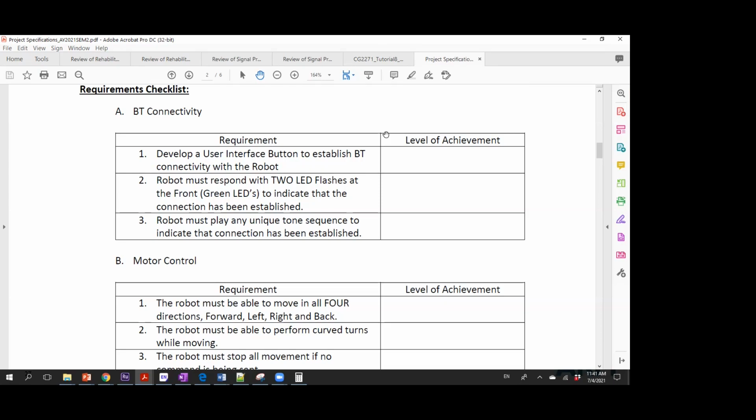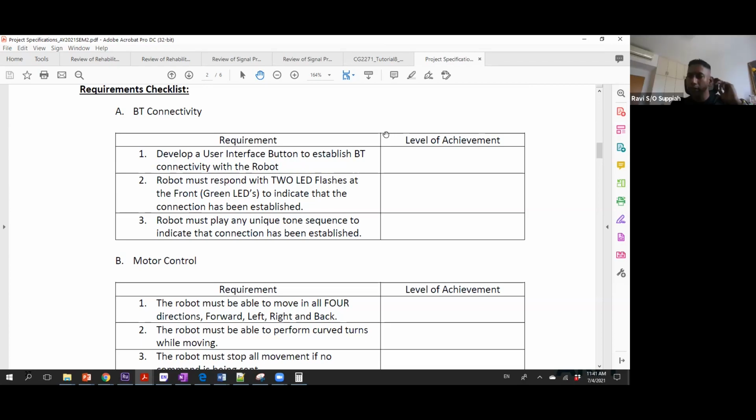Okay, this means the flag is just purely to tell it when to start, but it doesn't dictate what it does. So that's dictated by the message queue. Okay, message queue is different from the thread flags. Correct. In a message queue, you are sending some information, and the other person is supposed to receive and decode the information, and then decide what to do next. So if you use a message queue, when the task receives the message and it unblocks, you can also decode the message at the same time and decide what to do.